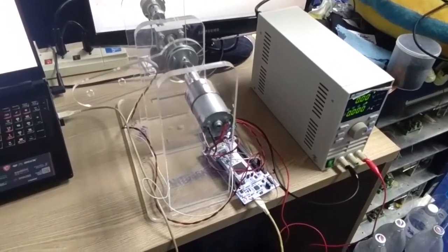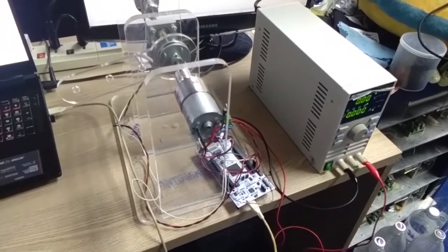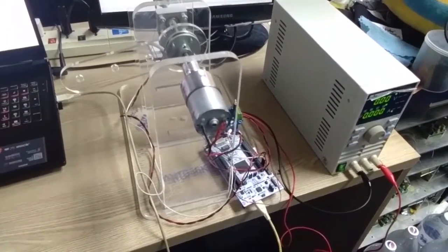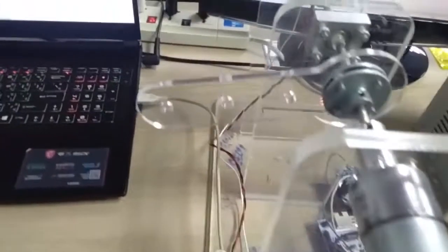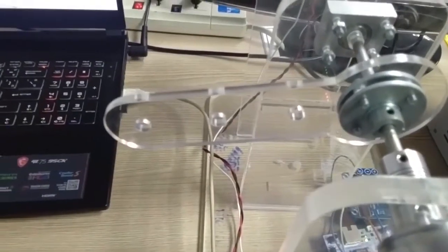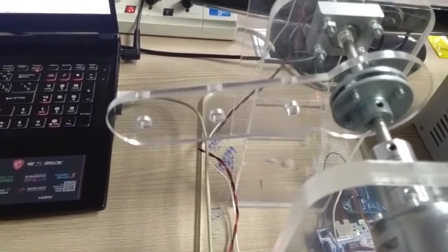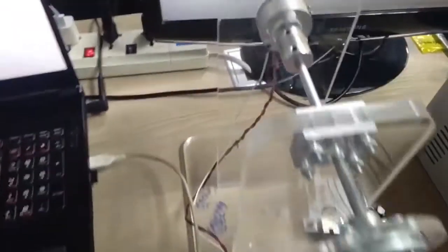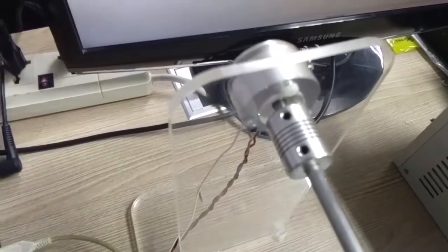Next step, we are going to do a PID control with a real system, which is composed of a DC motor and a closed loop system. In this experiment, we have a station where the motor is attached to a linkage for checking the rotation position. We will control the position by commanding the motor to move the linkage to the desired angle. We also have a potentiometer which gives a zero value at the end of each round.